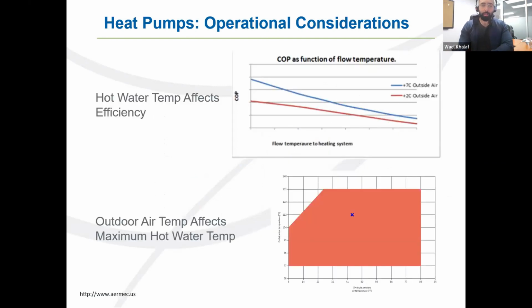So it's not only outside air that has an effect on the COP. Here we have another chart on top that shows the effect on the COP versus the outlet water temperature. As I want to increase my supply water temperature, or my outlet water temperature, the COP will decrease since the compressor must work harder to produce a higher supply water temperature using the same amount of heat in the outside air. So again, same concept we talked about in the past slide, but shown a bit differently, by talking about how we can reset that supply hot water temperature with respect to the ambient temperature outside.